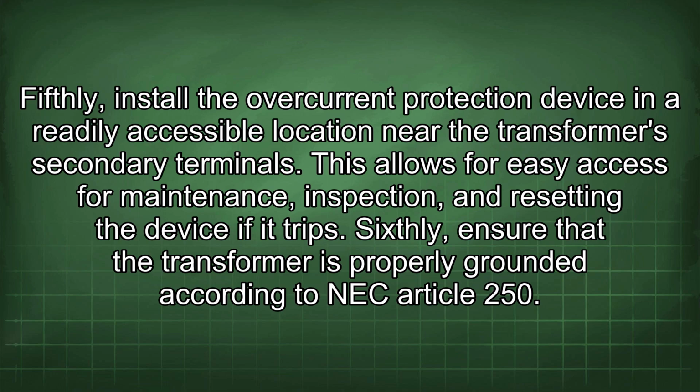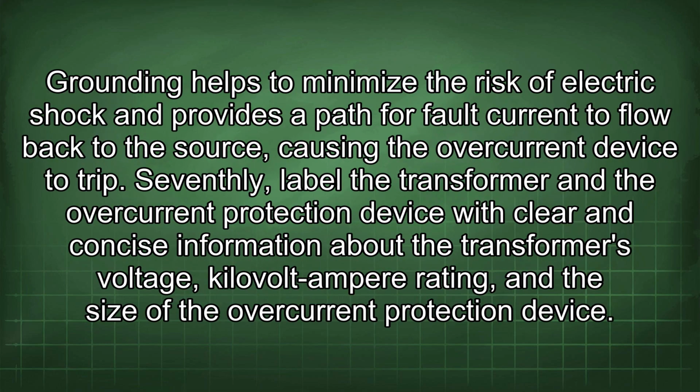Sixthly, ensure that the transformer is properly grounded according to NEC Article 250. Grounding helps to minimize the risk of electric shock and provides a path for fault current to flow back to the source, causing the overcurrent device to trip.